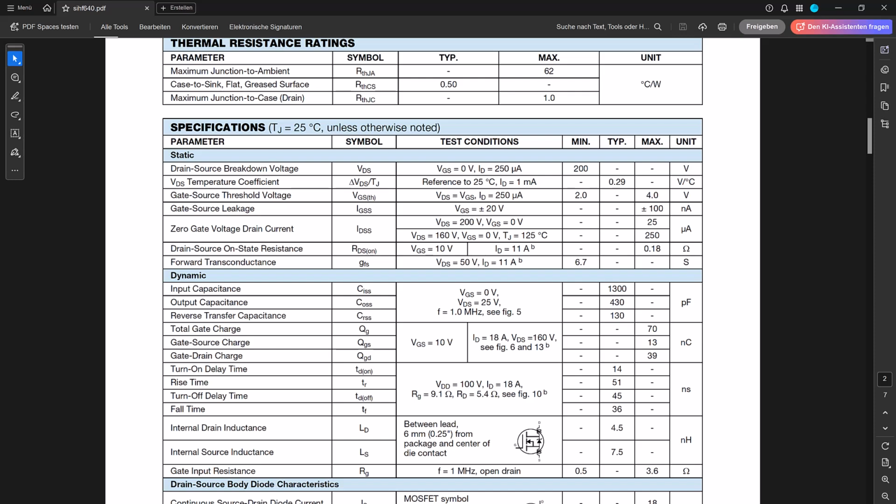And another important detail, hidden in a figure later. VGS(th) decreases with temperature, roughly 4 to 6 millivolts per degree Celsius. So at 100 degrees Celsius, the transistor opens at a lower voltage than when cold, critical for hard switched applications.